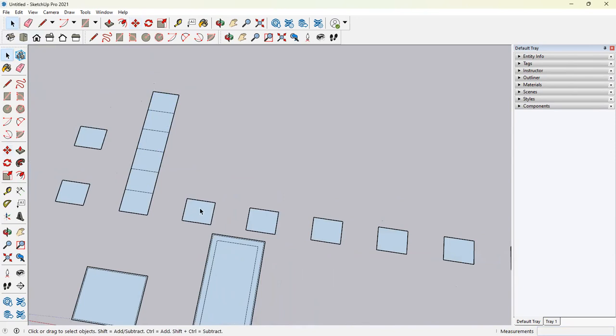Now, if you want to divide the distance, so let's say maybe this is like a rafter or a column. I get the move tool active, control. Let's say that it's showing me that it's at 66.5 feet. So I press it. Now I do slash, that is divide, and 5. Now what it will do is it will divide that distance into 5 equal parts. And you already have your geometry that has been divided. You don't need to do the math.